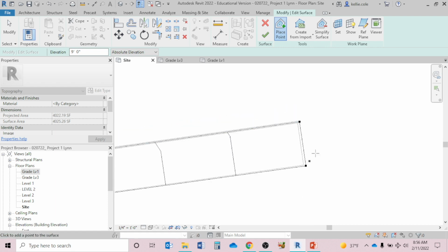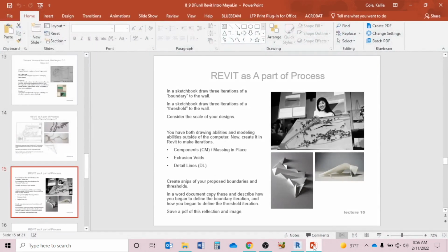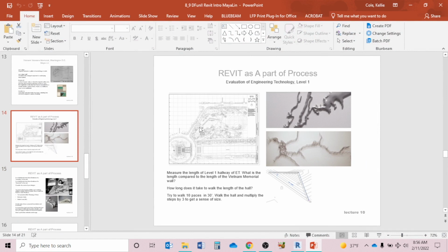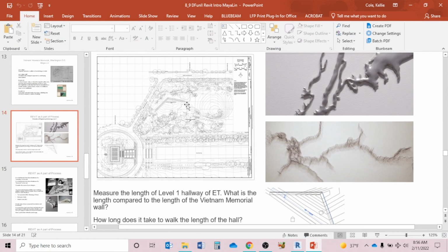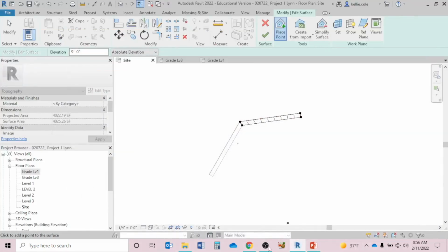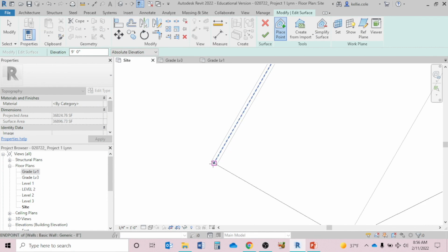Also on the other side of the sidewalk, you can see that it begins to develop my slope. I'm going to imagine, because I look at the topography in Maya Lin's drawing here, that topography makes an arc connecting the 2 arms of the memorial. So I'll place a 9-foot dimension out here and repeat that on the other side of the wall, hovering at the midpoint.